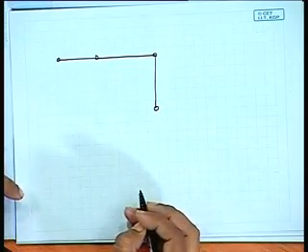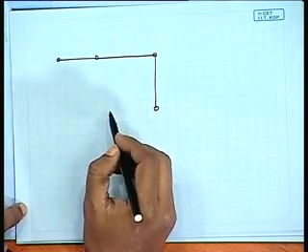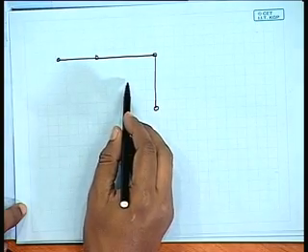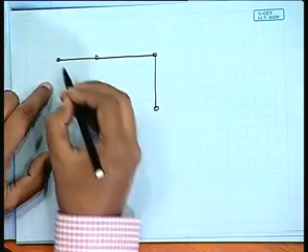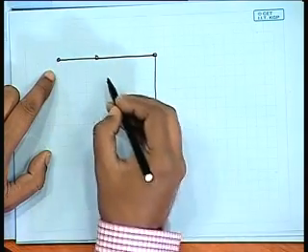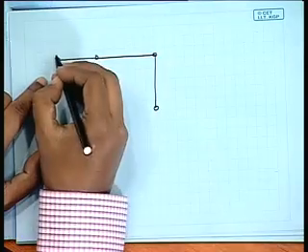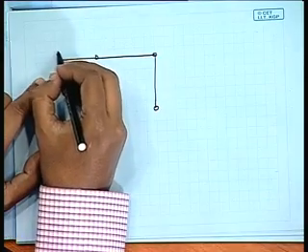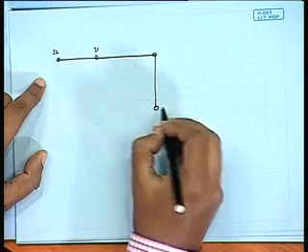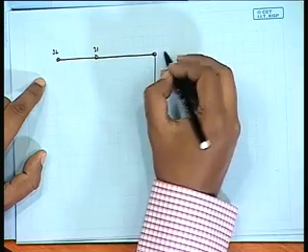In cases when the plots are in a perpendicular fashion, it is much easier to find the equipotential line, generally done in a grid pattern. So you can always find the values like this. Say for the same case, here this one is 32, this one is 31, this one is 31, this one is 31 and this one is 30.